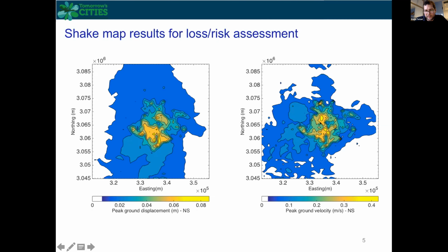And this one over on the right is showing the peak ground velocity of that. I didn't present the peak ground acceleration because of the fact that this type of simulation is valid up to, based on the investigation that I've done, up to 2 Hertz mostly, but the peak ground acceleration is affected by more high frequency, around 10 Hertz and more. Because of that, I haven't presented that. The additional work that is going on is to incorporate the stochasticity of different components in order to have a reliable estimates around the peak ground acceleration, which I think is usable for the type of vulnerability assessment that has been going on. Probably Ramesh will present something about this.